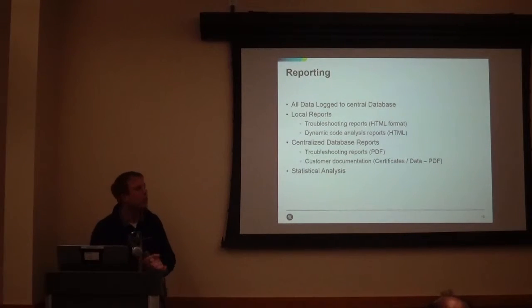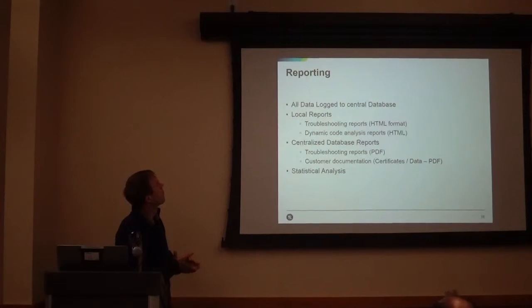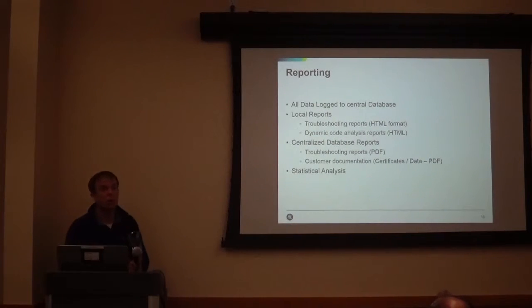Reporting side of stuff. With TestStand 2010 or so, things got a lot easier with the results processor plugins. Everything that we gather gets logged into a centralized results database. You do end up running local reports, HTML reports for troubleshooting and some code analysis, similar to TestStand sequence analyzer type of stuff.